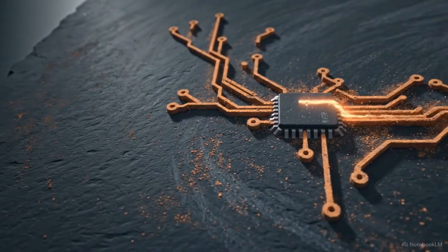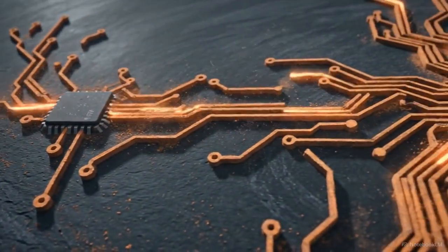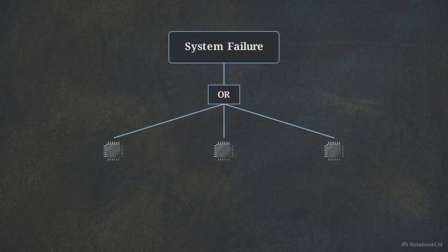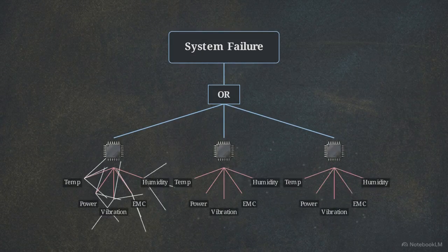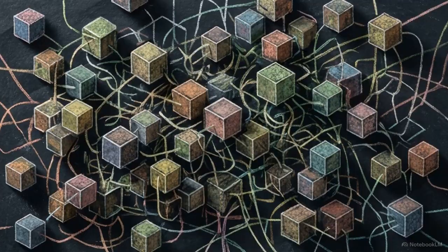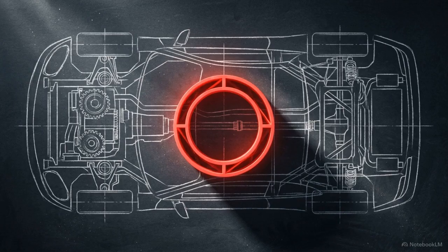Applying that level of modeling to a modern billion-transistor system requires processing power and timelines that far exceed practical engineering schedules. Attempting to force variables like temperature and power fluctuations onto every component branch causes a state explosion. The fault tree multiplies until the diagram becomes a dense, unreadable forest of data. Forcing secondary faults into a quantitative matrix destroys the tool's utility. It generates a mathematically invalid hardware metric and hides the actual architectural weaknesses engineers need to fix.